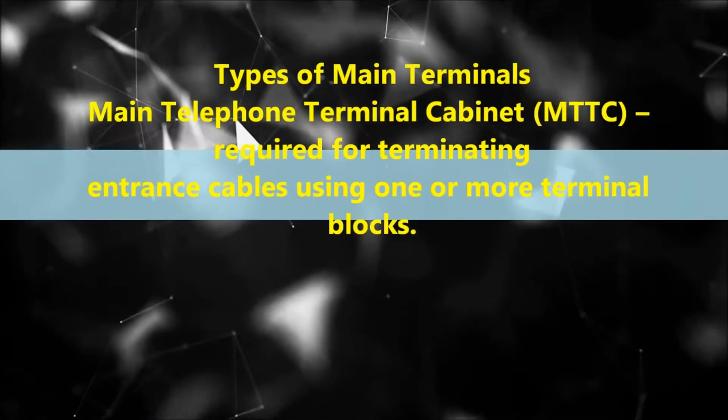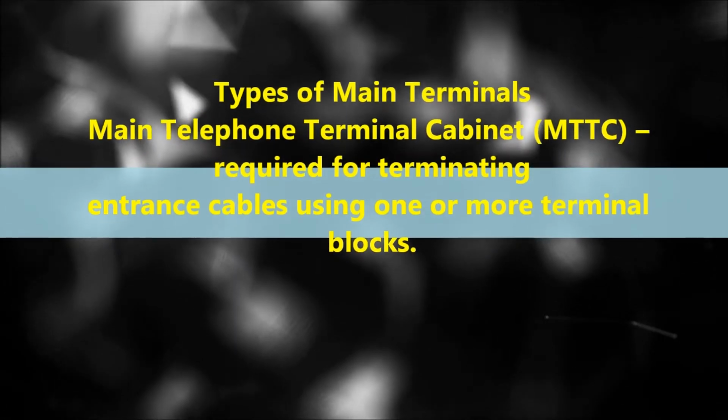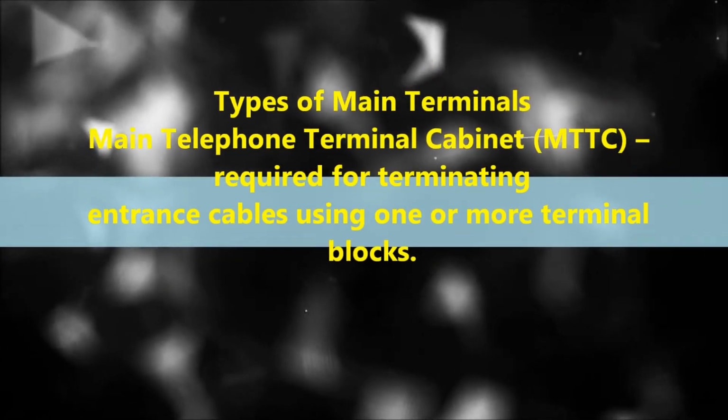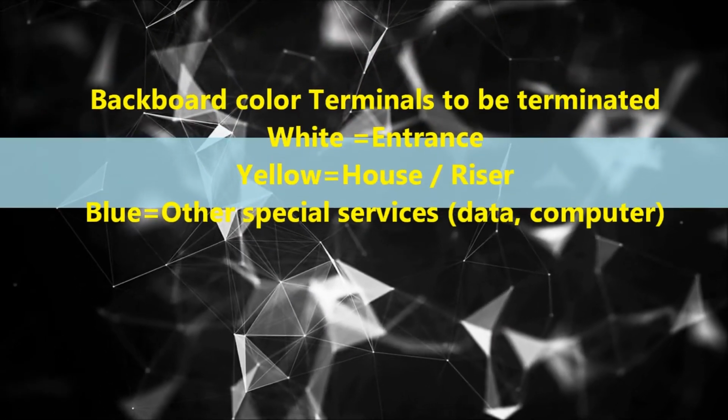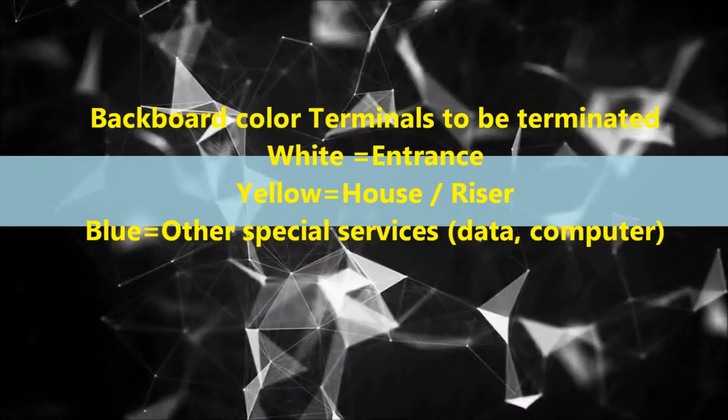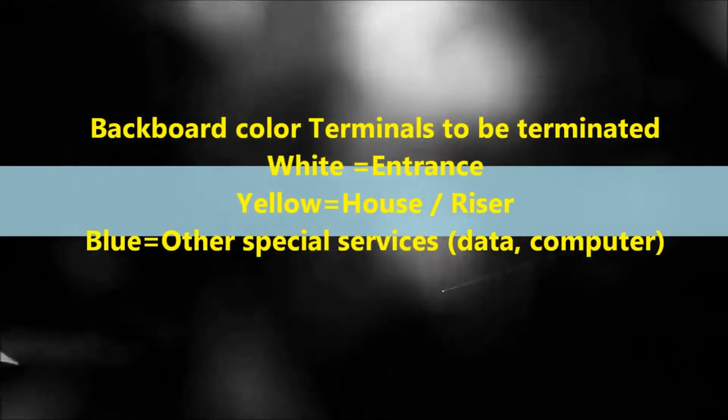Types of main terminals: Main telephone terminal cabinet, MTTC, required for terminating entrance cables using one or more terminal blocks. The color for the entrance terminal is white, yellow for house or riser, and blue for other special services like data and computer.